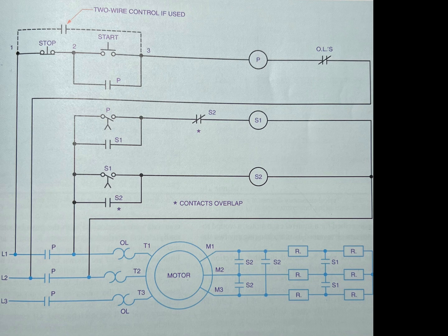When these timing relays are properly adjusted, all starting periods are the same regardless of the variation in the starting load. This automatic timing feature eliminates the danger of an improper start-up sequence by an inexperienced machine operator.